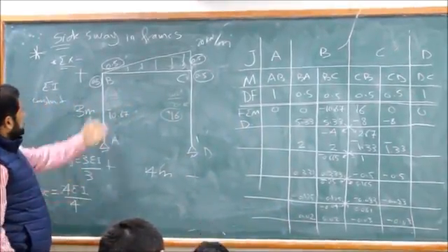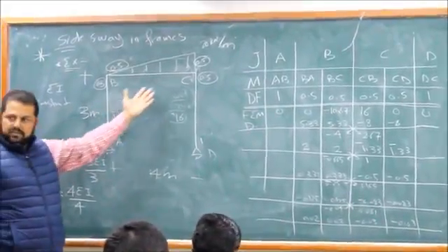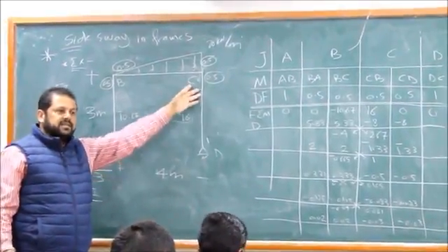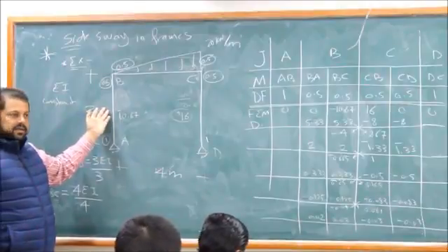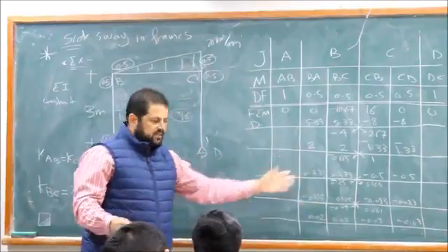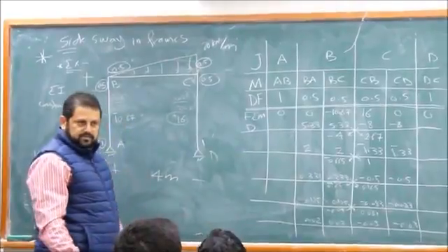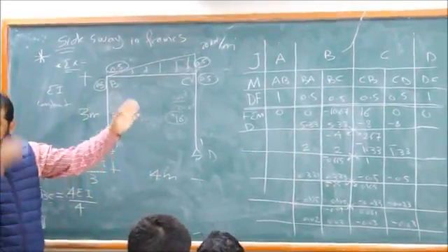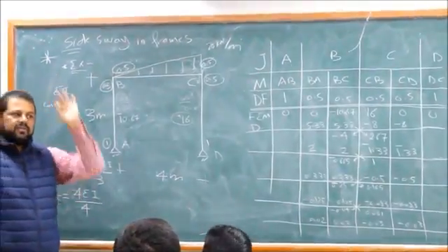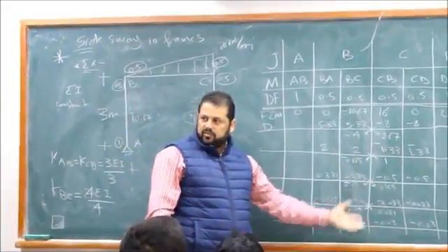Why? We expect the moments to be within 16 and 10, right? The moments within these numbers, and our moment values are 10 here, 16. We don't have something like 160 or 107 here. So if you have something like that, you can stop here, depending on how significant. But once you are below 0.1, you can stop. It's your judgment. We said this is an approximate method. You can carry it all the way. If you run a program in an Excel sheet, it will give you the exact answer. But approximate, who cares about this very small amount?